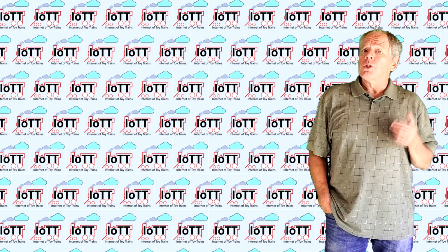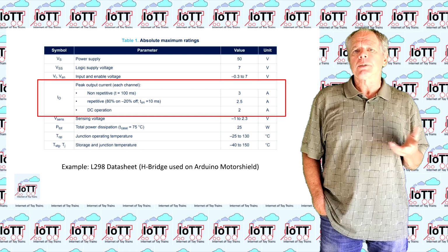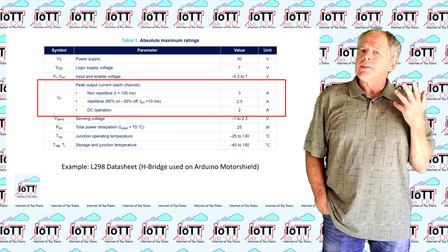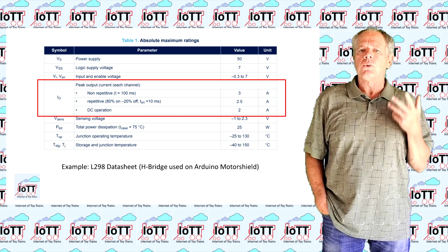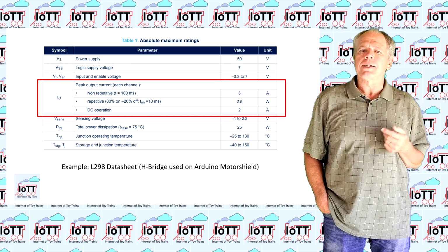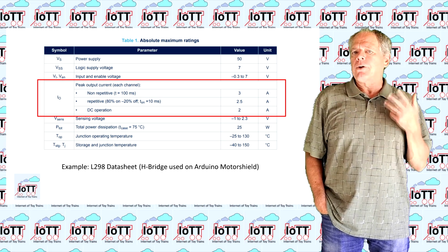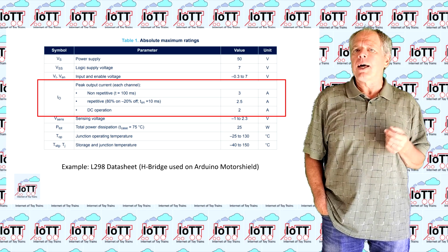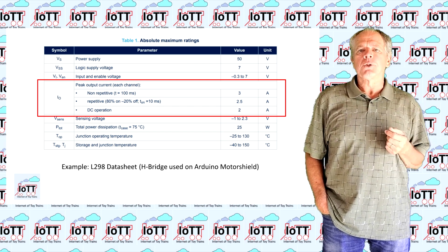Now, when it comes to a short circuit, things are different compared to the analog systems we covered before, as the transistors are much more sensitive to high currents compared to relatively insensitive wires and the like. If a short circuit happens and the current through the H-bridge multiplies, it will burn much faster than a typical fuse.